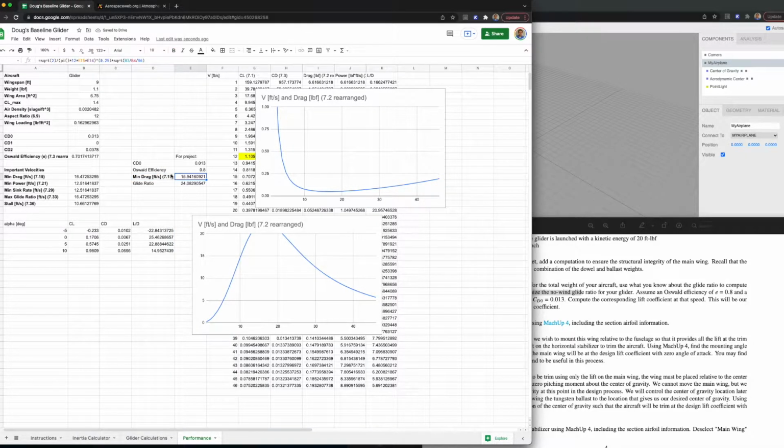Okay. For an Oswald efficiency of 0.8, the 0.8 drives what I sometimes call CD2, and so that's probably, I don't know, maybe a 0.03 here would give us 0.031, 0.032, 0.033. Okay, so that's about it. CD2 of about 0.033 gives us an Oswald efficiency of about 0.8. So I'm just plugging in 0.8. Doesn't matter. There's different ways you can type out this equation, either in terms of CD2 or the Oswald efficiency.